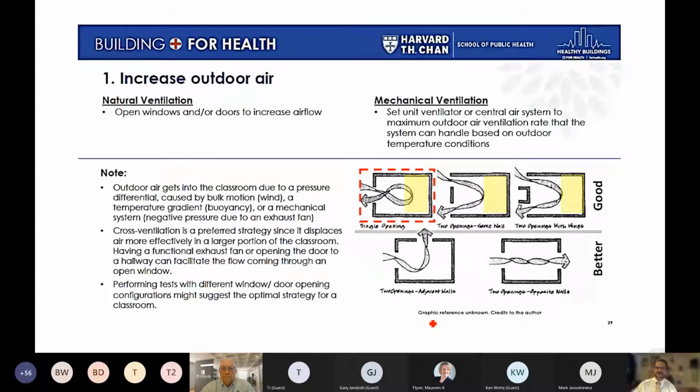The MIT study also shows opening a window with a fan. And in that particular case, you would be actually pushing air into the room, but it has to have somewhere to go. Even if you had a fan that was coming into this room here, if the rest of the room is sealed, once it pressurizes, there's really not going to be much more air coming into the room at that point. So the difference between heating and cooling, outside cold air and inside warm air, that's one effect. The second effect is oxygen and CO2. That's an indoor air quality effect, which no matter what air you bring in, you'll be increasing oxygen relative to the CO2 level. That's good for general IAQ, but for the virus, bringing in more particles is problematic. And by opening up the windows, we will be bringing in more particles.